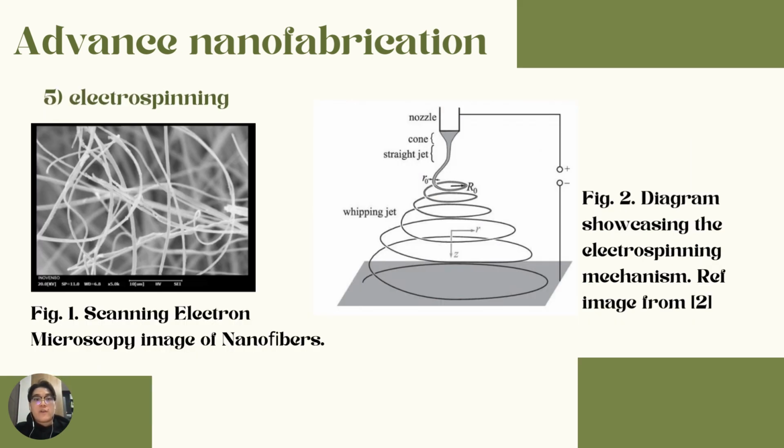After we do FIB milling, they can be put into a polymer solution and electrospun to produce composite nanofibers with embedded carbon nanotubes. The carbon nanofibers can be created after a second carbonization phase.